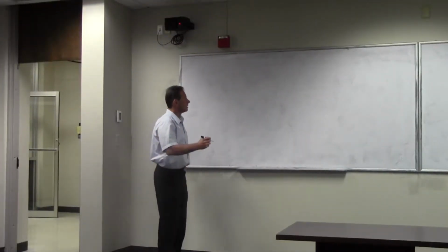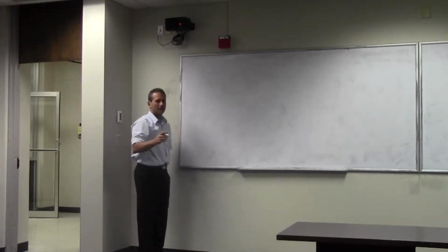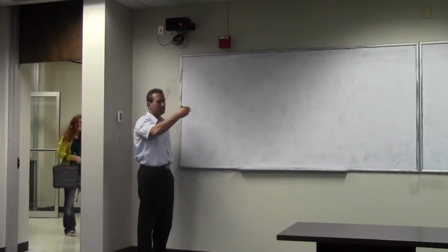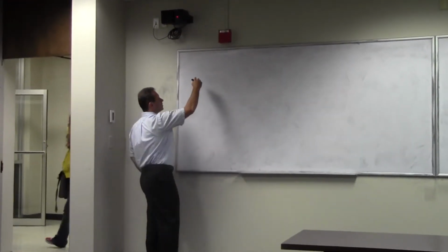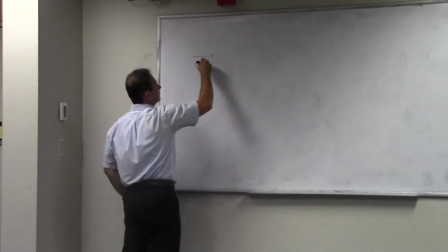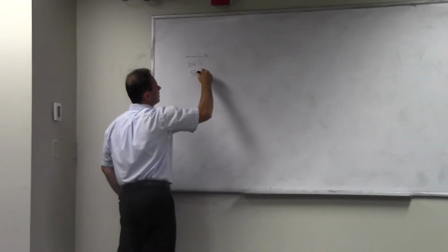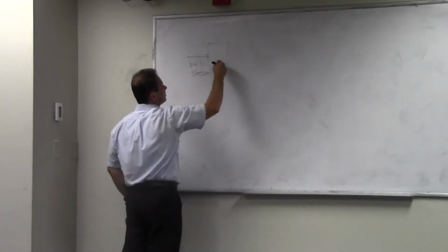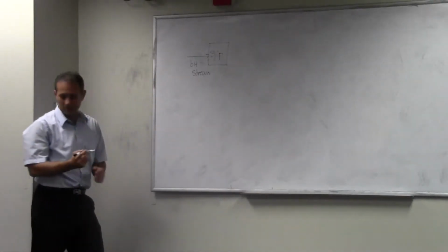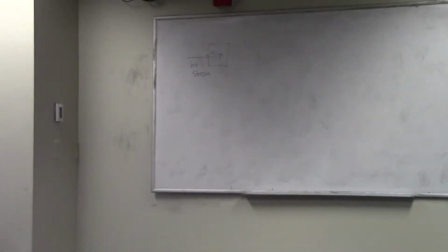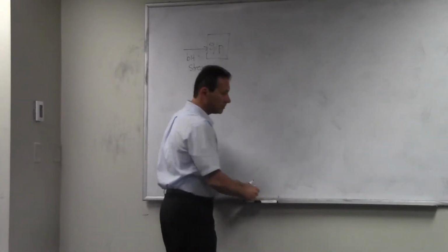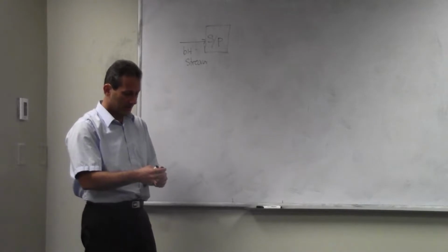The question is to go over again quadrature modulation, and the question is just how do you map these bits into symbols? So here's our quadrature modulator. You have your bit stream coming in, and then you have this element here, which is called a serial-to-parallel converter, which actually performs these calculations. It is mapping a certain number of bits into an appropriate point in the constellation space.